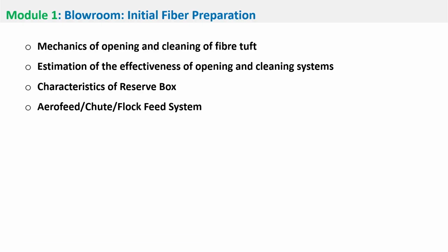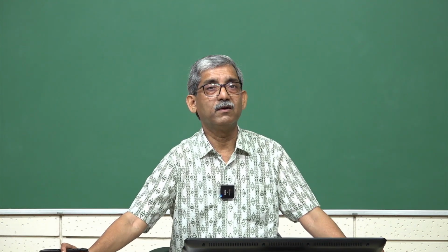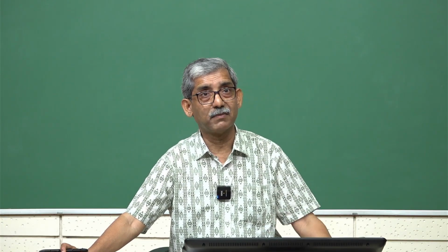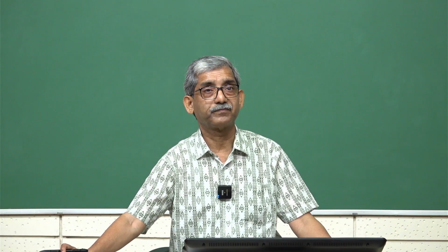Then the air feed, chute feed or flock feed system, which is actually from the blowroom, how the fiber transportation is controlled, that we will discuss. Then blending is an important part of blowroom. How the blending takes place, what are the mechanics of blending, and how to select the blend constituents, that we will discuss. And depending on the blend constituents, the selection of the blending process changes.